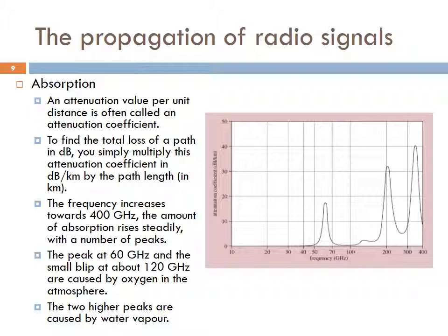For radio waves above 300 GHz, the losses are so great in practice that they are of no value for terrestrial communications. Lastly, note that figure 9 is for clear air. Rain, snow, fog, dust, and other atmospheric effects can all increase the losses by significant amounts.